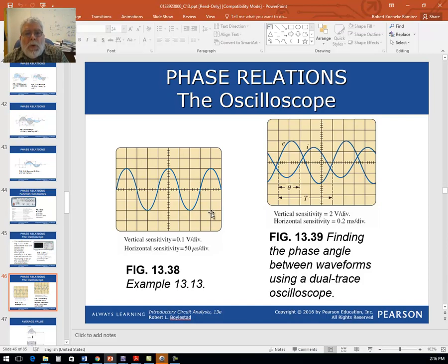Normally, you see that the screen here of the oscilloscope is a grid, and the grid has small squares. Those are the divisions. So if you want to read a value here, you need to read how many divisions. For instance, in this case, we have a sinusoid, and then we have one division from here, 2 divisions, 3, and 4.